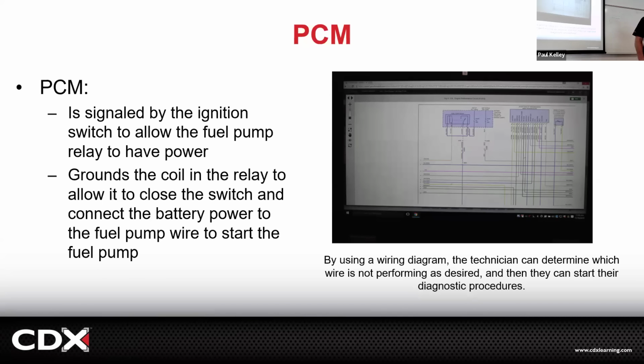And the meter is the main go-to if you know the fuel pump doesn't work. But if we back up, how did you know the fuel pump didn't work? If it did a crank no start, that could be no spark, no fuel, or no compression. True. If it's going into an anti-theft or immobilizer mode, it'll turn the injectors off because it thinks it's being stolen, right? So we can't just jump to, oh, it's a bad fuel pump.